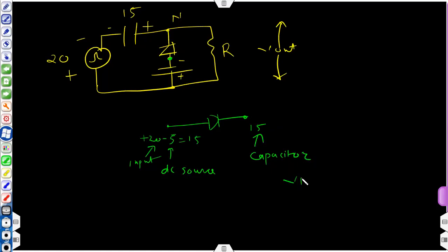So condition is Vp is equal to Vn. So again, this condition is equivalent to the reverse bias state. So diode will be off. And you can always remove the off diode from the circuit, so removing it, deleting the entire branch.